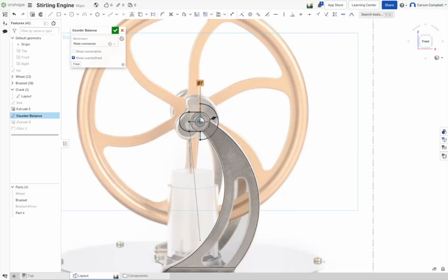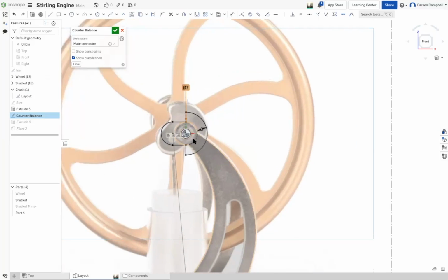Delete the diameter offset. So we have a diameter offset for the counterbalance slug, not that, but the 3. There's a dimension, that other one, pull it out, and lo and behold, it was a 3, so delete it. And now put in a dimension.